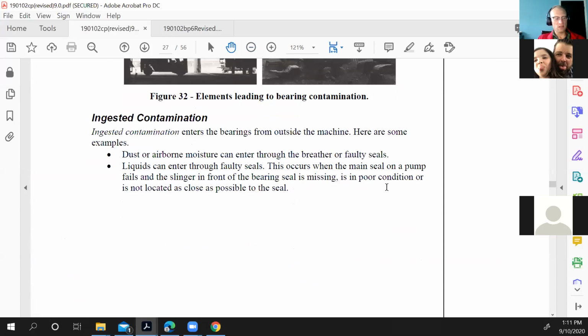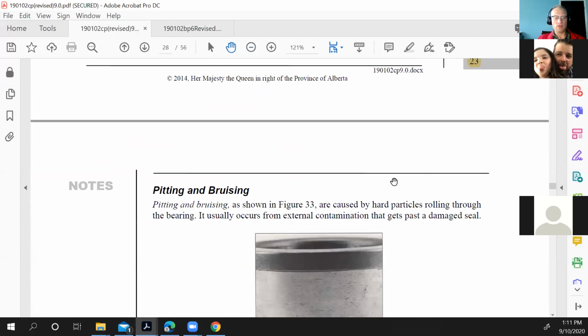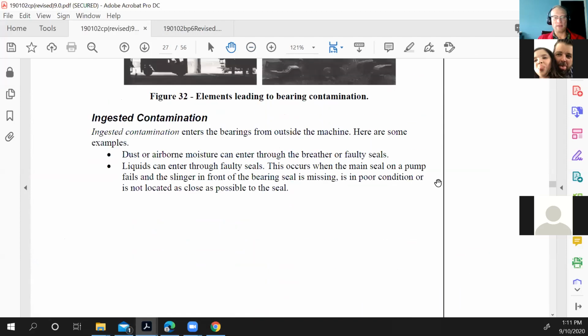So seals, we talked about how seals don't necessarily hold the pressure, and we have our vents that we need to vent out the excess pressure. They also do something else. So first of all, why does pressure build up in these cases? Why? Heat, yeah. So heat's generated when the bearings are turning around and around. The oil heats up, some of it vaporizes. As all that's happening, the gas inside of there is heating up as well, and it's expanding, okay? So that pressure needs to escape.